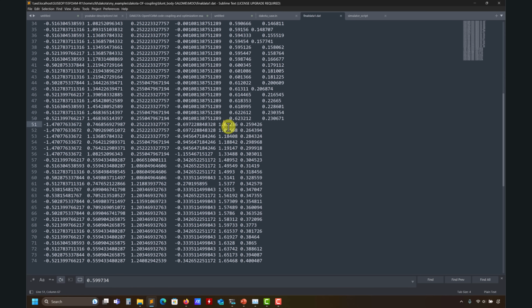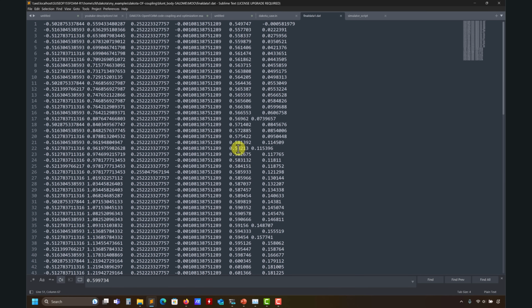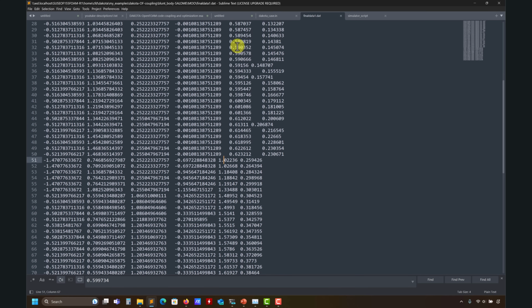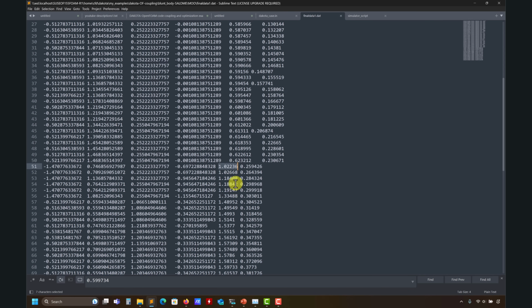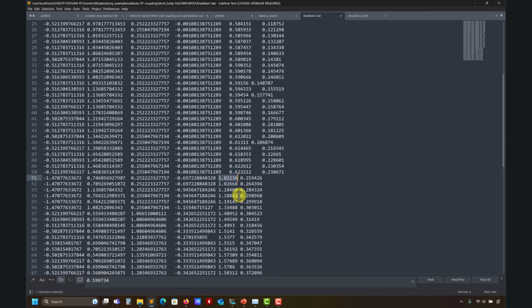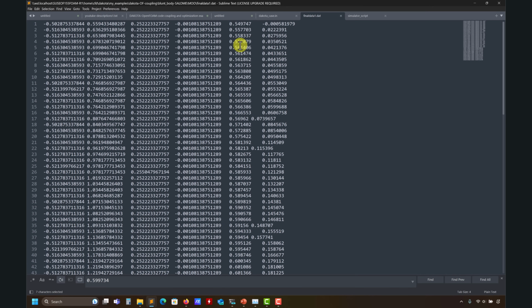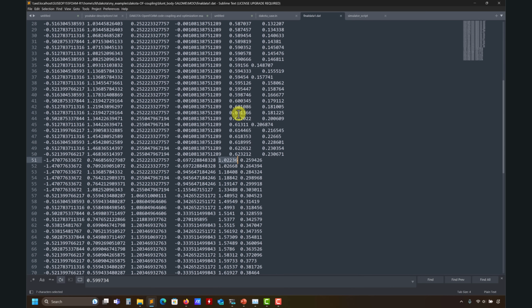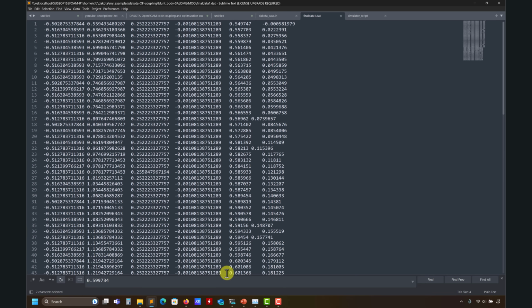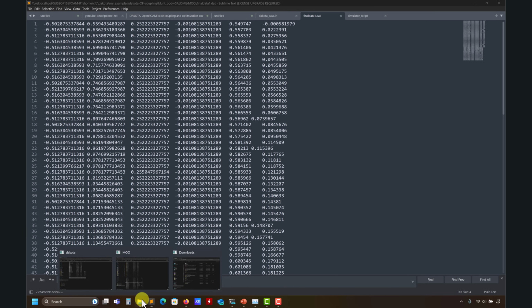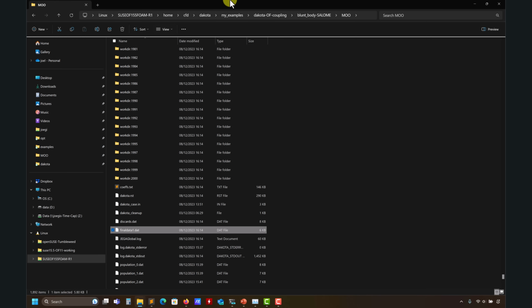So in all those function evaluations that the MOGA conducted, these are also non-dominating. It's called a non-dominated solution. It cannot get any better than this. So you will have all these possible solutions, and at this point it will be up to you to pick which one you would like to use. You don't have a single one, you have multiple solutions. So let's do some plotting about this to show you the Pareto in this case.